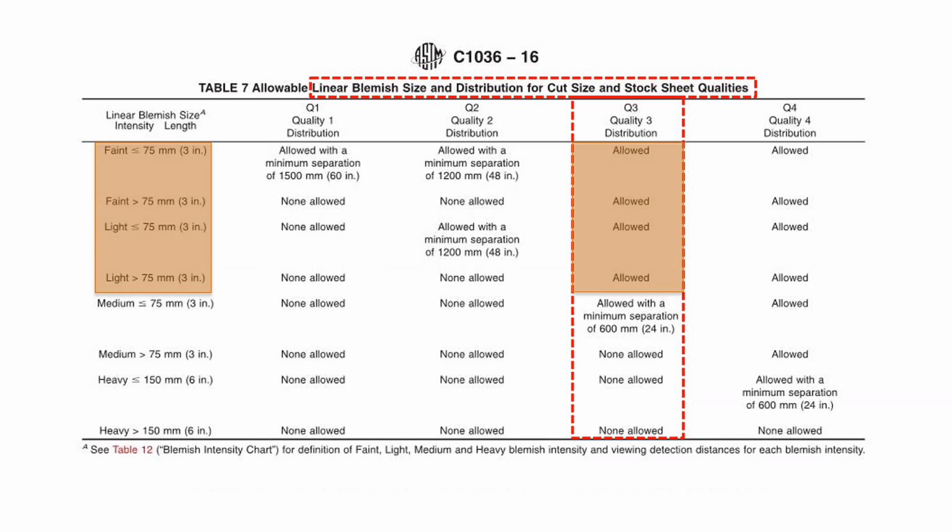So this is all to point out the fact that glass is not manufactured, transported, or installed in such a manner that it's going to end up on your building facade in a pristine condition. There may, in fact, be relatively large blemishes that are allowed that may predate any significant event, like a natural disaster. So that's important to realize as well.